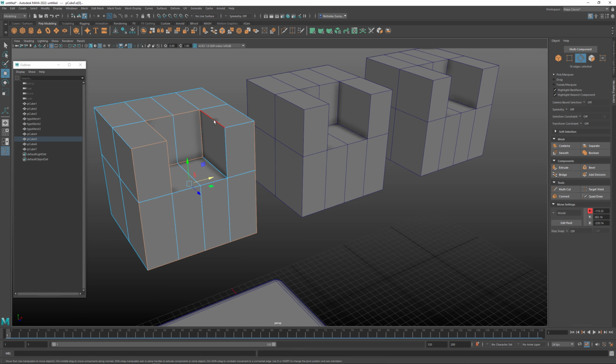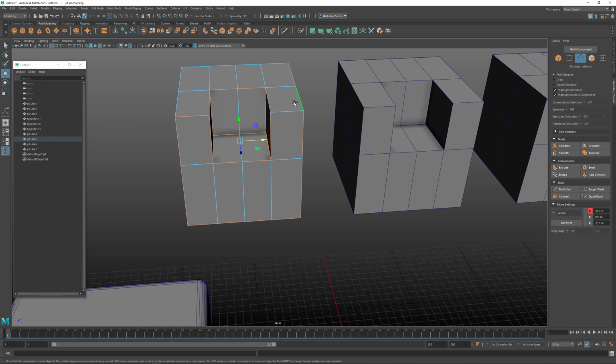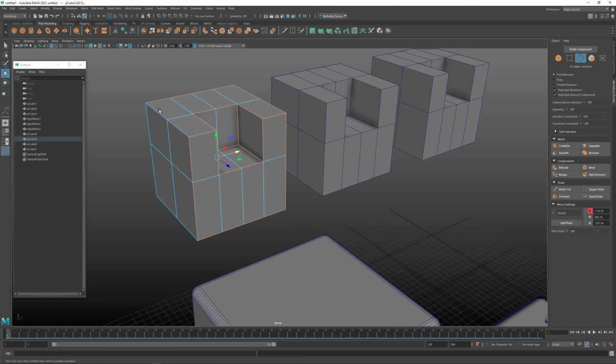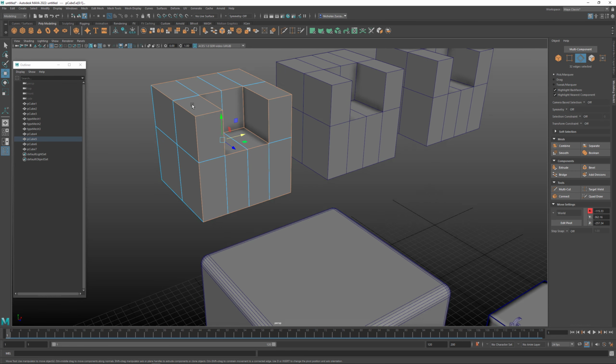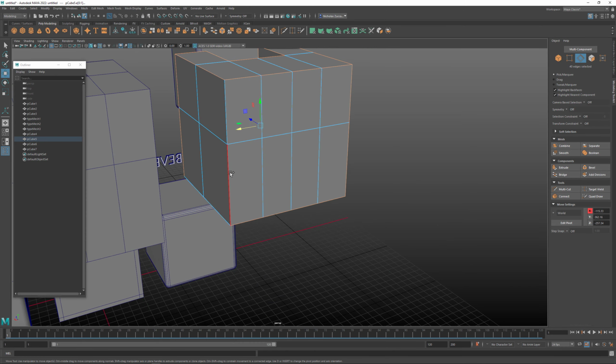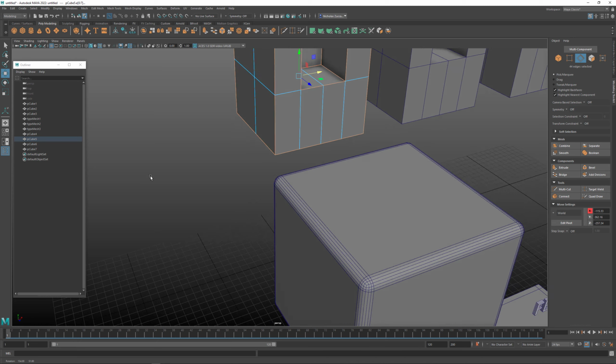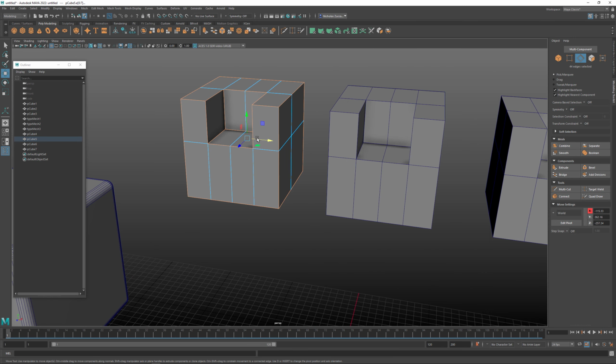It's going to take a little bit of time, and hopefully you can see what I'm trying to select. I'm just trying to select these outer edges like this and get this all selected up. And I'm moving around the object, holding down shift and double clicking, and it's adding to the selection and getting some edge loops on here. So I've got everything selected like this.